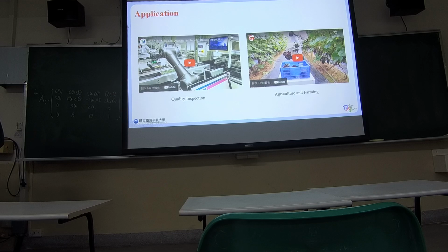And cobots also prove their value in quality inspection. In the electronics manufacturing industry, cobots are often deployed at the end of production lines to inspect the quality of circuit board welding, using cameras to identify defects. Cobots can automatically classify and sort products based on inspection results.